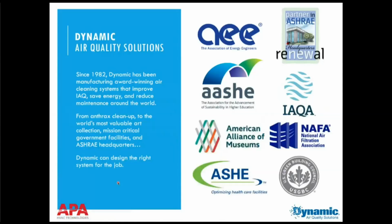We've been designing systems for a long time to clean air in buildings, and so basically we do 3 types of projects. We do new construction, where the deliverable is less fan horsepower and MERV 13 or greater filtration for a new building. We do energy retrofits in existing buildings, and also help with filtration upgrades in those. And then another subset is helping customers with IAQ issues, diagnose and solve those. So we've always been providing clean air. It's just usually people have been asking us, in recent years, what's my ROI? Now people are more interested in the air quality aspect.